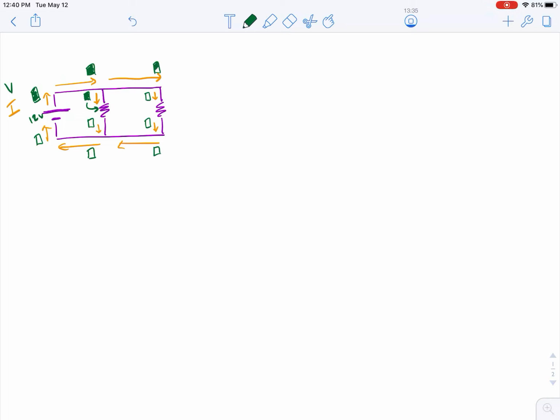The second branch has its own set of electrons, which currently have full cups of energy. So they come down this wire with full cups of energy. Now they are also only going to encounter one device. So all of that voltage is dumped into that second resistor. That means that these electrons are going to come out with 0 volts remaining. So if you were to be asked about what is the voltage drop or what is the voltage across resistor 1, that would be 12 volts.